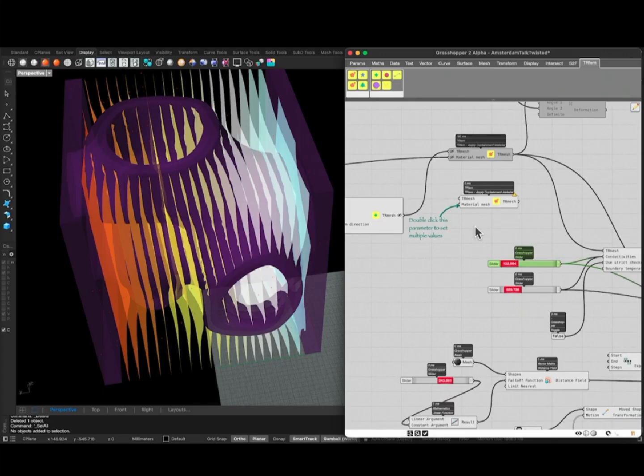Okay, so this is the component here that will take a TRfem or TRmesh tetrahedral mesh, and it will take a mesh that encloses the volume we are talking about, and will just apply all these material indices. So this is also extremely painless. There's no fumbling around with any kind of large indices or very obscure VTK file formats. I mean, I love VTK file formats and so on, but I think this one is a little easier. Cool, thanks. Check it out and let me know.